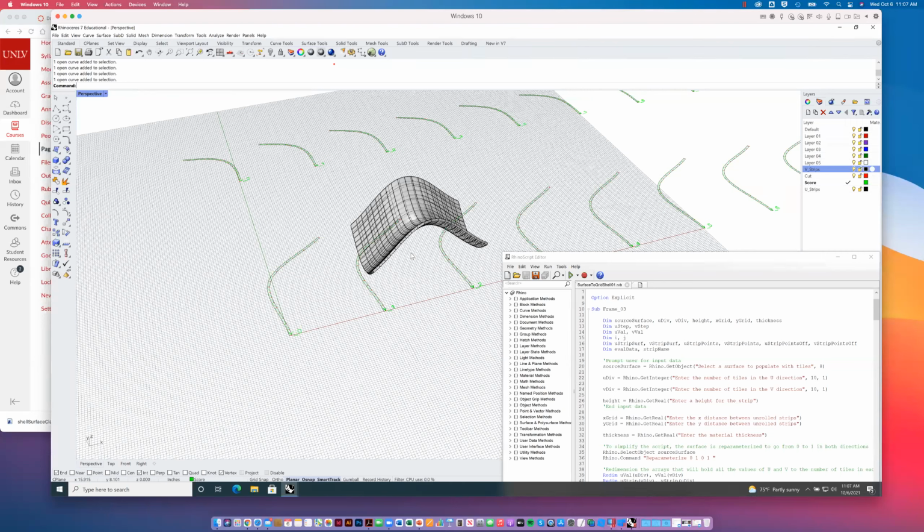You can run this script again. It only takes a few seconds each time, in order to look at what you get and make a decision. What do you want? You could do it 12 times or 15 times or 20 times or 10 times, to look at that density and the spacing, and pick something that you like. But I will say for the U divisions and the V divisions, it needs to be at least 10, no more than 20. I'll just give you that range to work within. That'll help you and save you some time later on, okay?